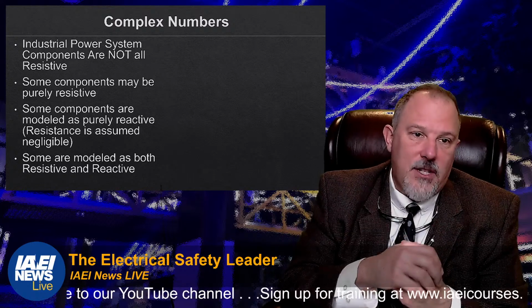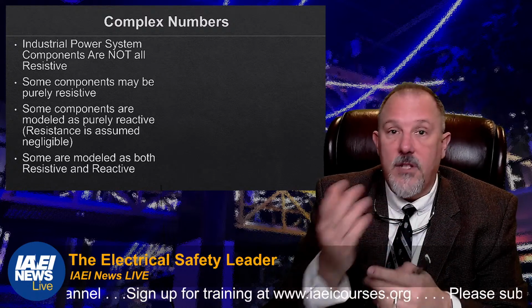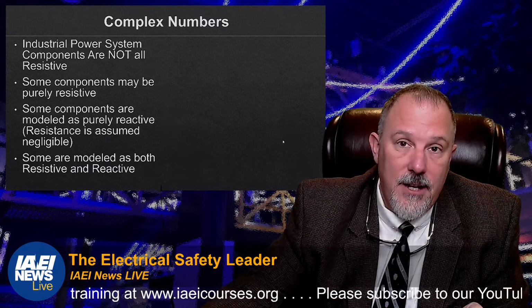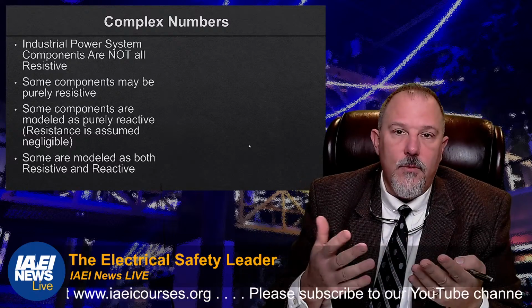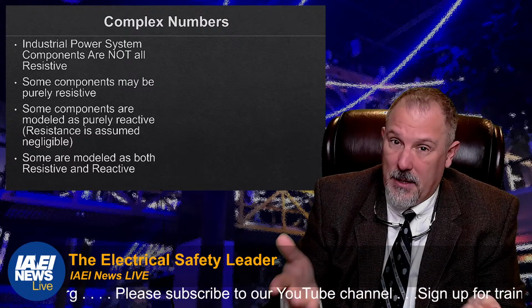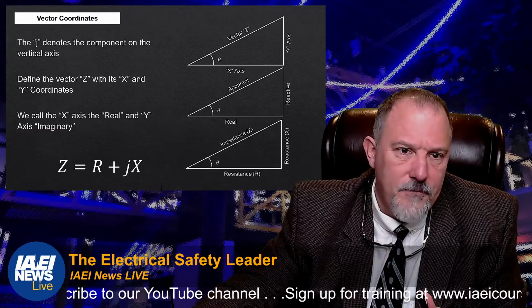Not all of the power system components are resistive. Some of them might be purely resistive. Some of them might be resistance and reactance. Some we might just model as a reactance, like a transformer. We don't typically model a transformer's resistance. Not typically. If I have a software application, by all means.